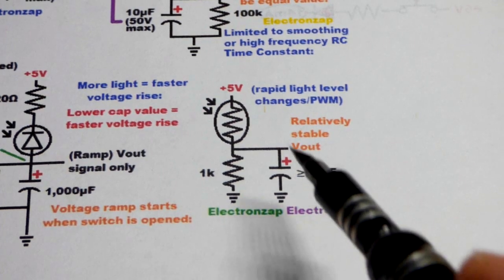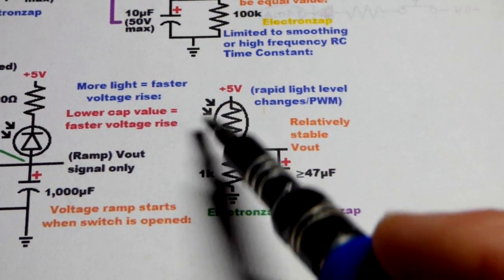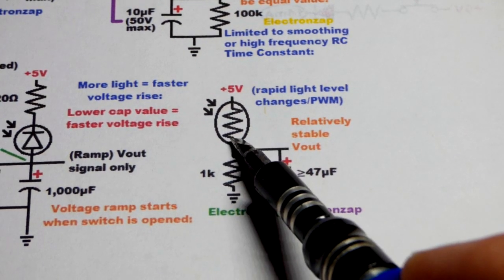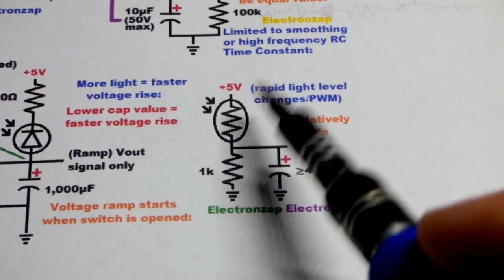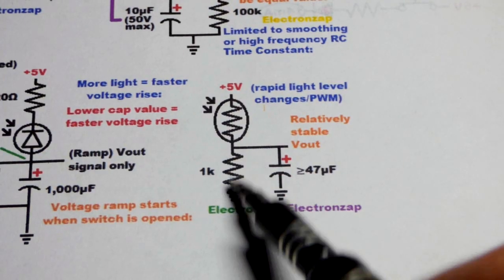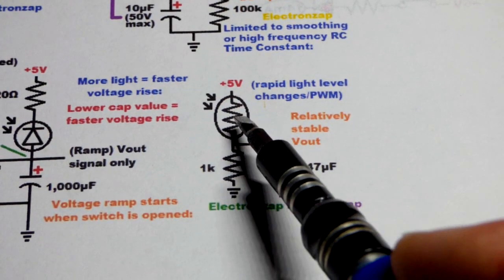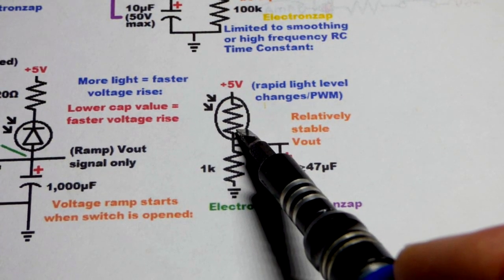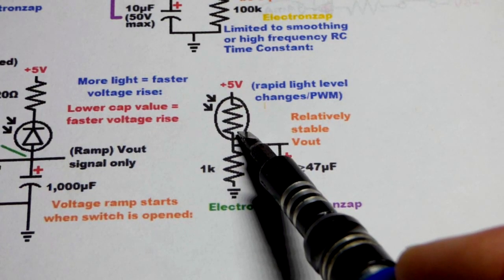So now, if you have a circuit that responds to light, a lot of times you use a light-dependent resistor. So its resistance changes depending on how much light is falling on it. More light, less resistance. When it's darker, there's more resistance. Often use it as a voltage divider. But often that light is not steady. It's kind of flickering, even though your eye may not notice it.